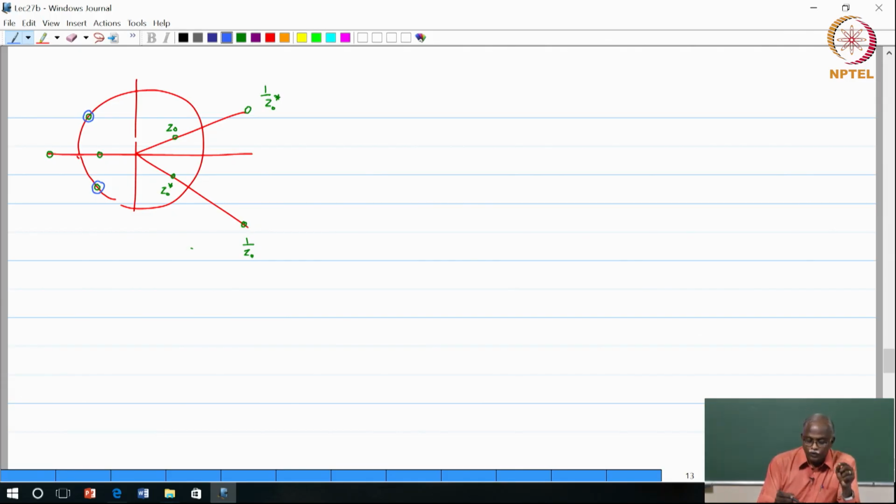Now, look at this observation. If I now have something of this form G naught of z, can I factorize it of the form H naught of z times H naught tilde of z? Which means every zero must either go to H of z or H tilde of z, and they must give you the same magnitude response.